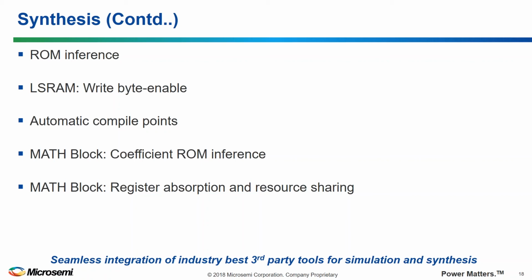It also lends itself well to a team application. If you have various team members working on different blocks and you define different compile points, then you don't have all the blocks being resynthesized all the time.